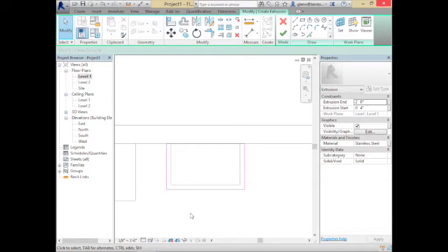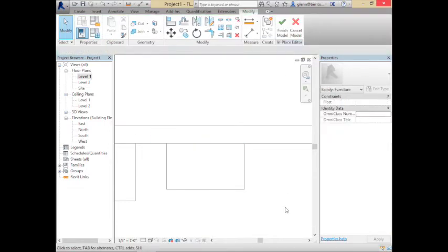So that's our tabletop. Now this one is not going to go from 4 to 2 inches. This is going to go from 2 feet to, how thick do you want the countertop to be? Or the tabletop? It's your table. You get to choose. 1.5 inches. Okay, sounds good. So here we'll actually put in 2 foot 1.5, so it's very explicit. It's not relative. When we start creating our own families, we'll do that as a relative thing, where we just say the thickness of that countertop. Here we have to give it the dimensions in global space. Does that make sense? Okay, last little piece, or almost the last little piece.